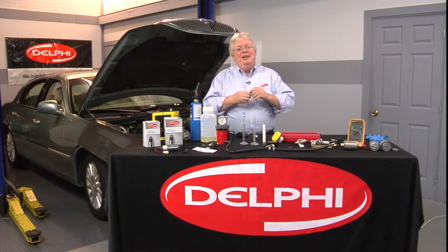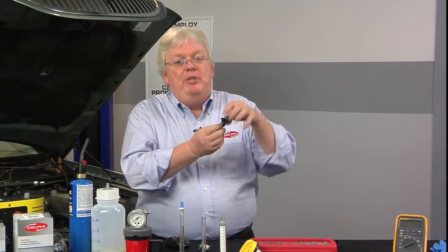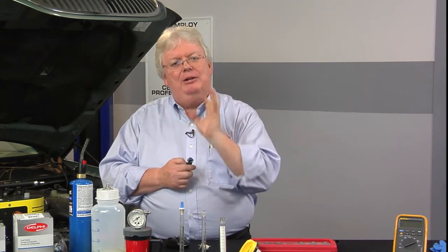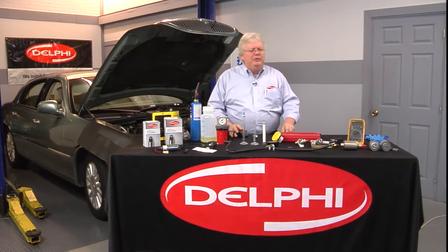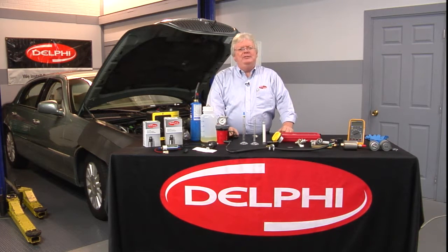The one that looked good was good because the drippy injector was being leaned out so much with the base pulse width that dripping and a little bit of spray was just the right amount to give it a good pattern. So keep that little nuance in mind as you look at your patterns if you're doing fuel trim and you've got a scope you're used to putting on ignition and looking there. That's a view inside the combustion chamber using that scope.